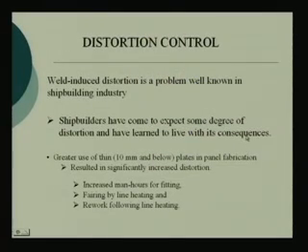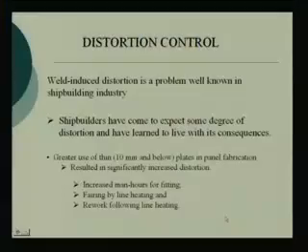It will happen, and wherever it is unavoidable, you try to implement fairing measures, distortion fairing measures, that means line heating, and there is no other method, because by hammering you cannot straighten it, impossible. So, the only method is some thermal treatment, you cannot take the structure back to the roller and straighten it, right. Anyway, that is the basis of it. And then what we see is greater use of thin plates in panel fabrication.